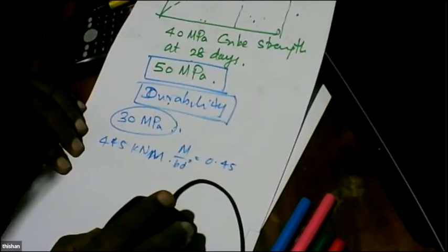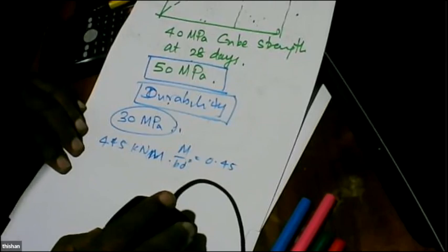Cars are 1.6 meters wide. So the dominating vehicle is the bus. So if the bus is 2.4 meters wide, and you have only 3 meter lanes, then the lane is too narrow. So it's better to go for 3.5 meter wide lanes. So if you are going to have 3.5 meter wide lanes, it's better to have the beams spaced at 1.75 meters. Is that clear? Yes.